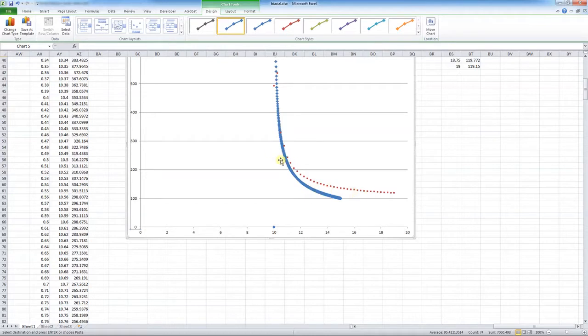near the crack tip. Again, I can't say this often enough, but the analytical solution assumed being extremely close to the crack tip. So we can use just regular elements to help us pick up a stress intensity factor. What you can do is fit this to a 1/r curve and extrapolate to find the geometry factor or stress intensity factor. But again, I want to point out that we use an extremely fine mesh.